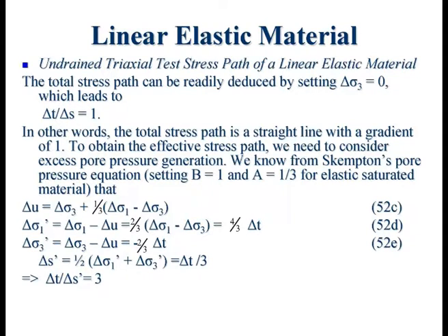Okay, and I want to, at this point, just make the important point, which I mentioned yesterday as well, and that is that regardless of whether you're using S and T or P and Q, you think of it this way: S and P is a characterization of the normal stress. It's some measure of the normal stress. All right. So S dash is some measure of the effective stress. P dash is some measure of the effective stress, except that they take different components into account. How you count that thing, what you put into the basket to count.